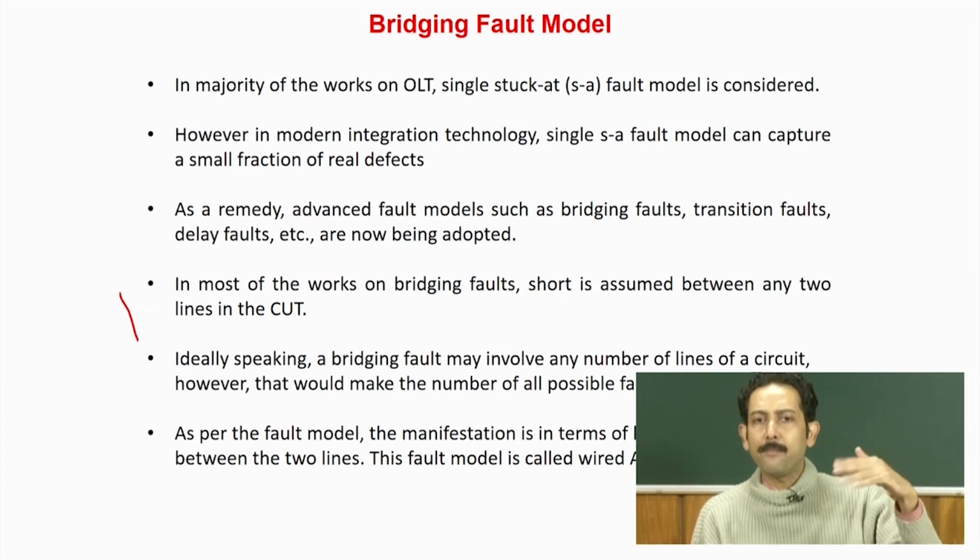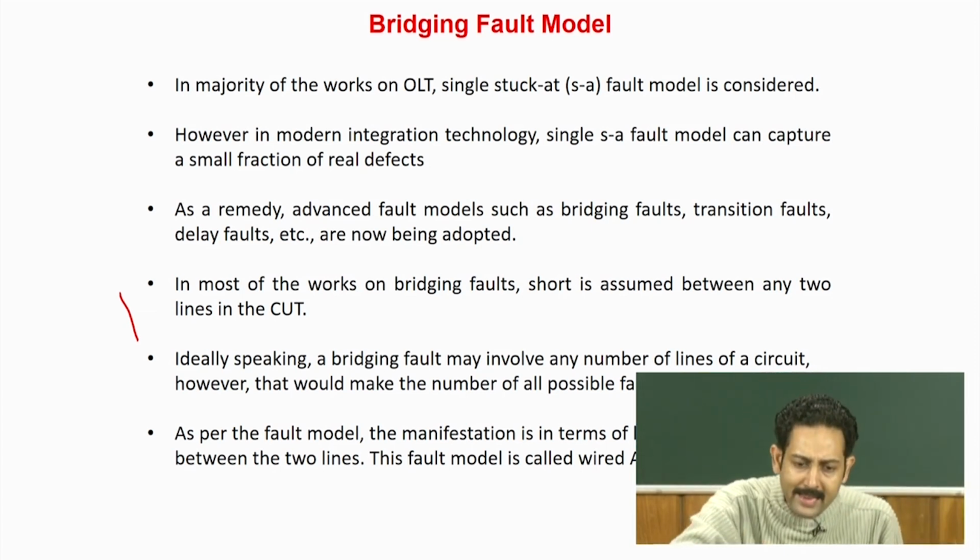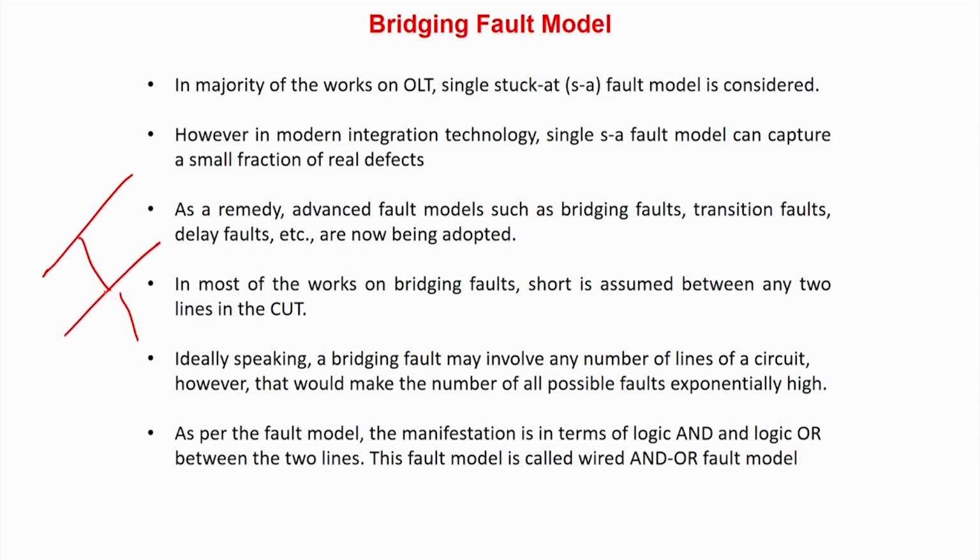The higher the micron technology, the more is the gap between the two lines laid out in the VLSI circuit. As the gap between the two lines is high, the probability of faults occurring there is lower, or even if faults were there, they generally led to lines being cut, that is a stuck-at 0, or sometimes something happened due to interference etc.